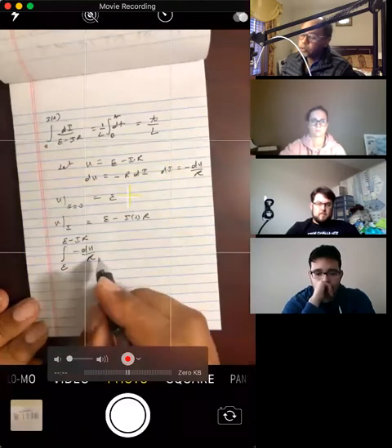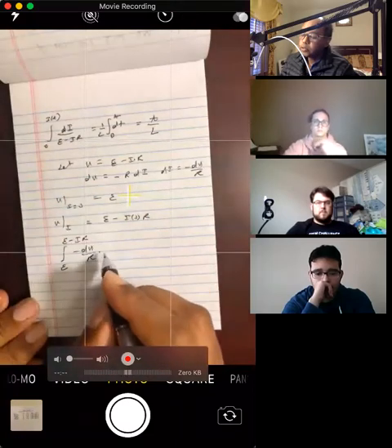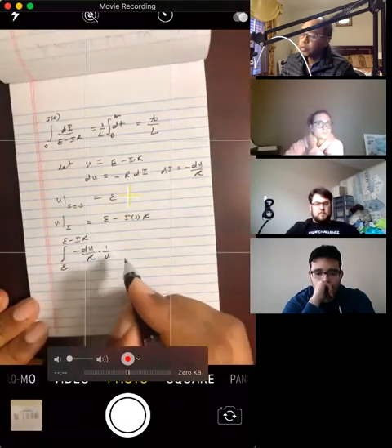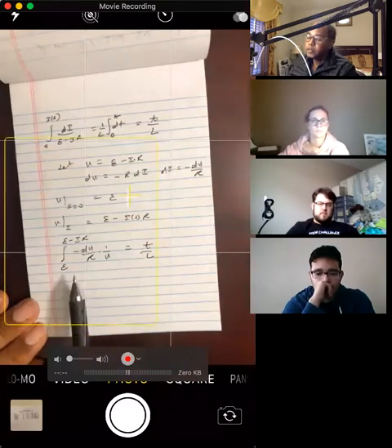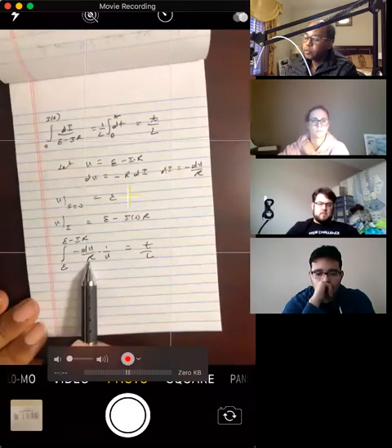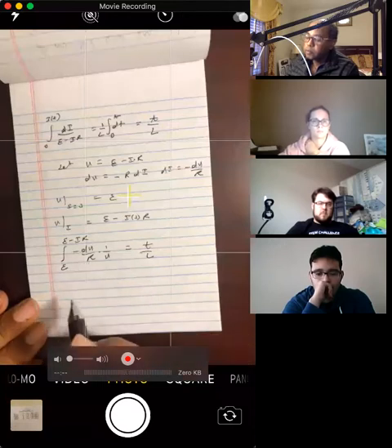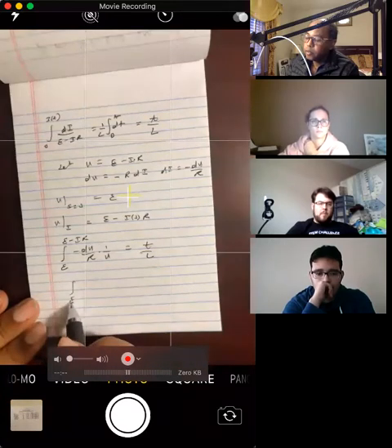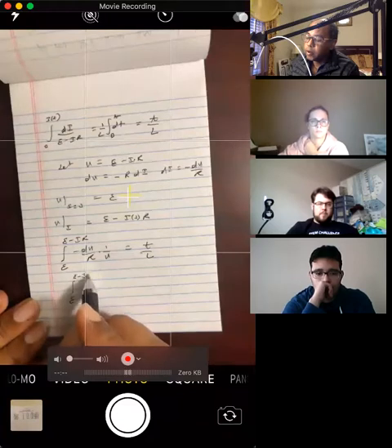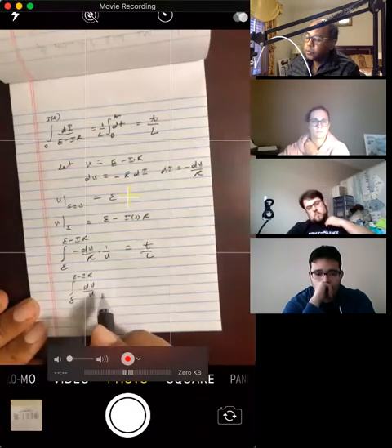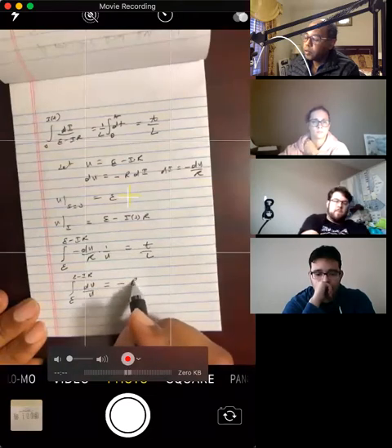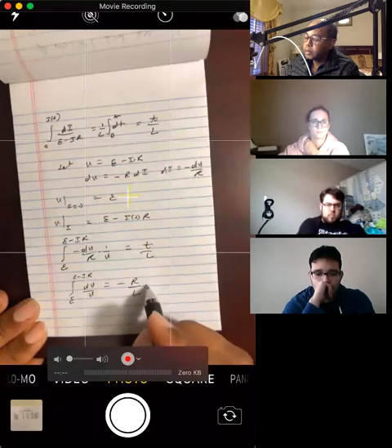And then E minus IR is u, so you've got 1 over u, and that equals t over L. Let's take out the constant, negative 1 over R. So this integral from E to E minus IR of du over u will be negative R over L t.